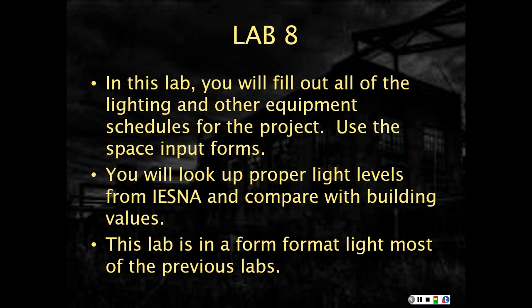Now in Lab 8, in this lab you'll fill out all of the lighting and other equipment schedules for the project. Again, you're going to use the space input forms. You're going to look up proper light levels from the IESNA and compare with building values. Now I've included as a resource a snippet of the IESNA handbook, where you can look up some lighting levels.